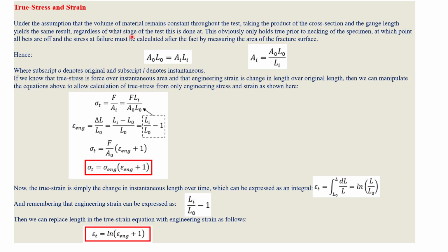In short, whatever we are doing in the static analysis, it's all related to engineering stress, engineering strain itself, because there we take the constant thickness, but if it is deforming, if it is under the nonlinear condition, then we consider the true stress strain. There we have the nonlinear analysis, the failure with respect to failure theories.